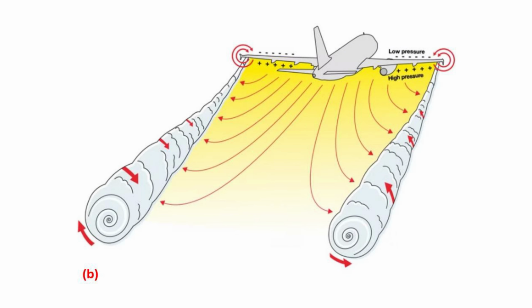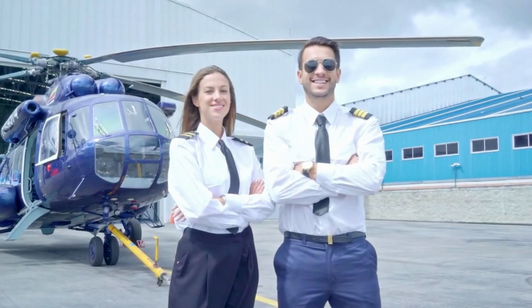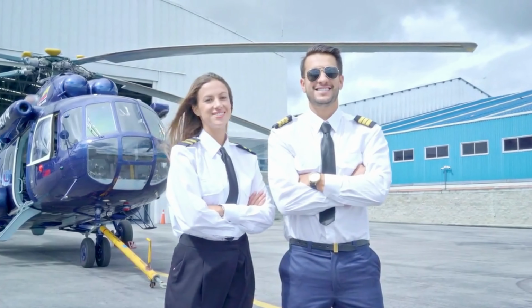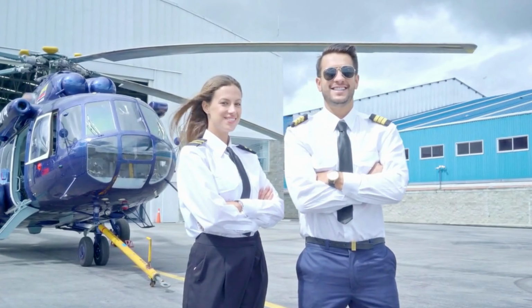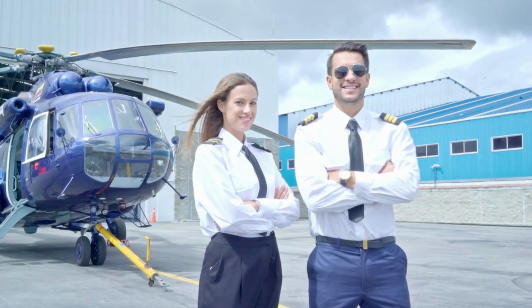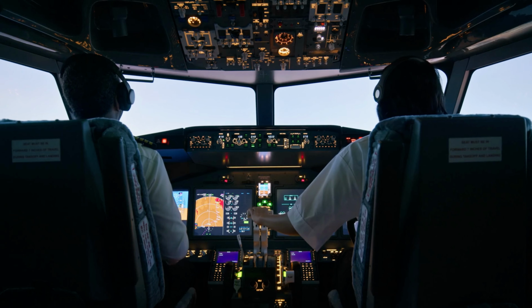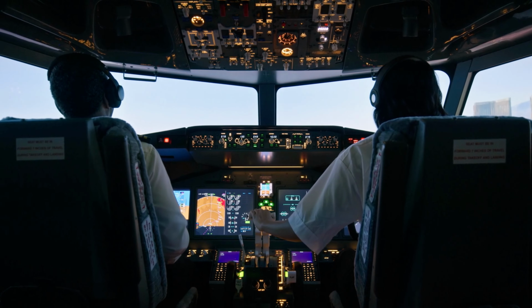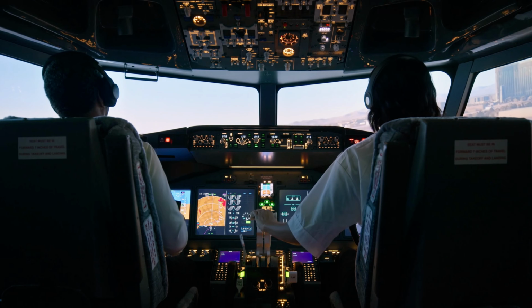Vortex behavior. The tricky thing about wake turbulence and wingtip vortices is that they are invisible. They can only be avoided by predicting their behavior. The pilots need to visualize the wake from other traffic and ensure that they are flying far enough behind for the vortices to dissipate from the leading aircraft.